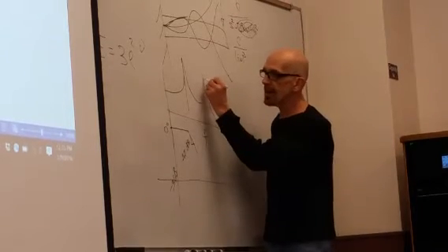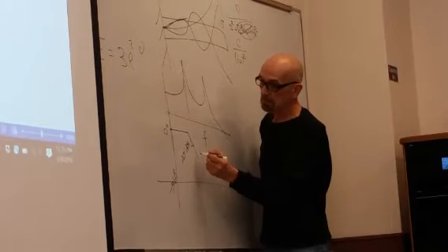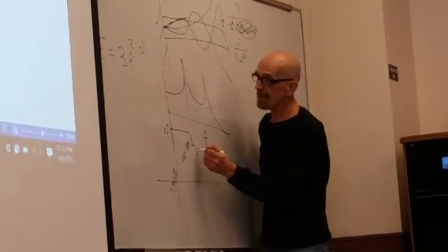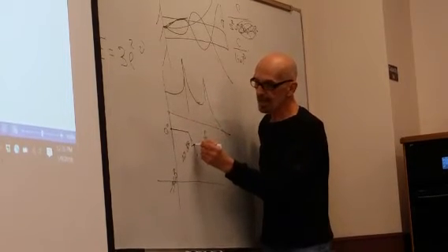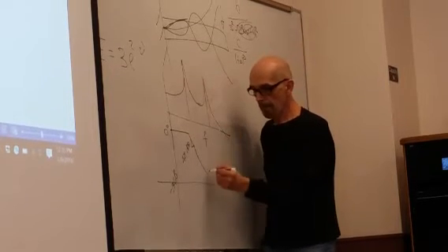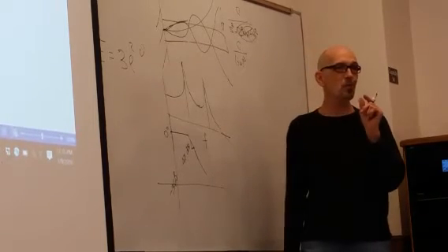But then you get to 1/10 of this break frequency, and let's see. Well, it's not actually doing anything, is it? This is just going to be a constant. So this thing keeps rolling down until you hit this one. Remember, with the magnitude, it's real easy.